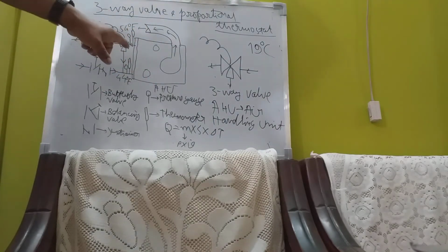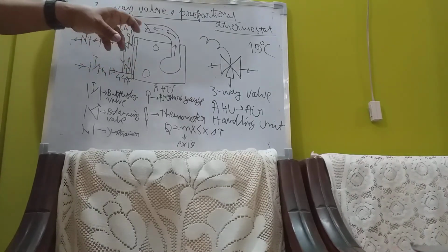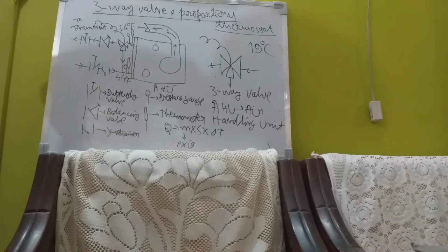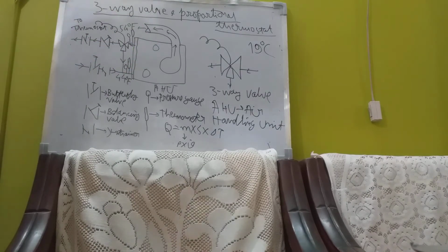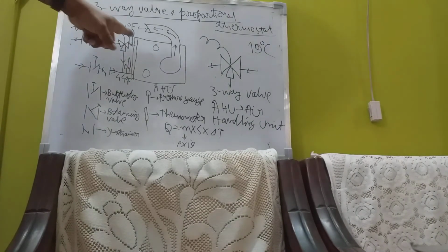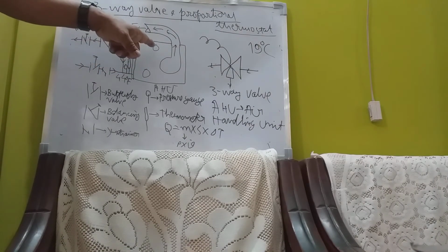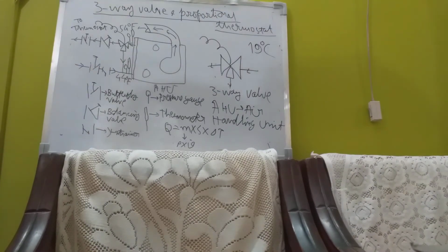In the AHU, one part is the three-way mixing valve, another is the cooling coil. Cooling coil is not manufactured by the AHU manufacturer. Cooling coil is manufactured by some other manufacturer. So the cooling coil has a particular capacity of temperature transmission. That capacity is delta T of 10 degrees Fahrenheit only. That delta T should be 10 degrees Fahrenheit, that it should be able to take a heat of delta T of 10 degrees Fahrenheit for a particular GPM, or gallons per minute, of flow.